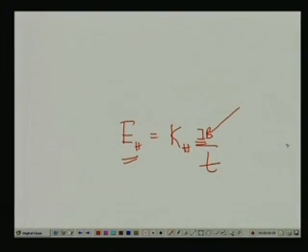Please do not confuse this small I with the actual current we are measuring. This small I is a DC current established in the Hall sensor by a steady voltage, which is a very small voltage. We are not measuring this current I; we are measuring a current which is changing the value of B, and we are measuring the EH. That may be associated with a large, fatal voltage, but it will not come to the sensed output.